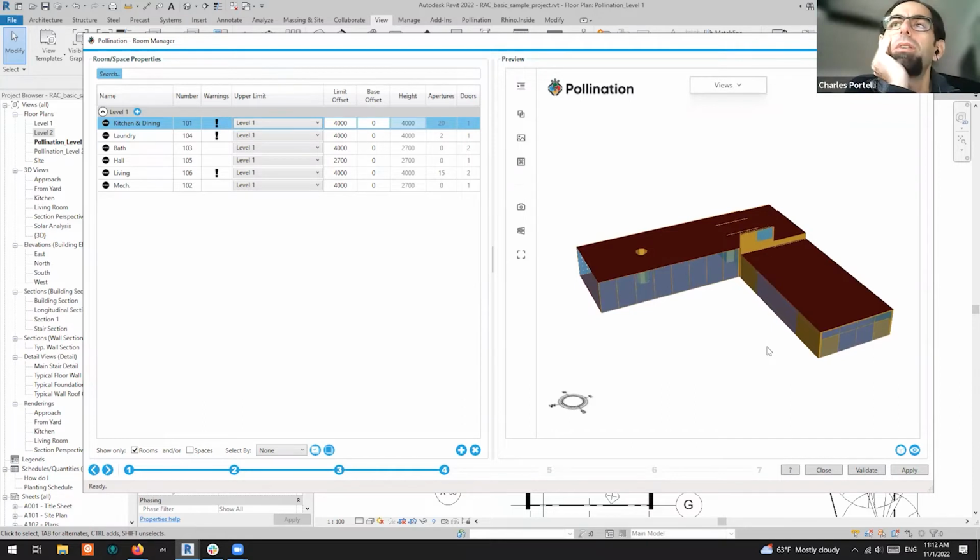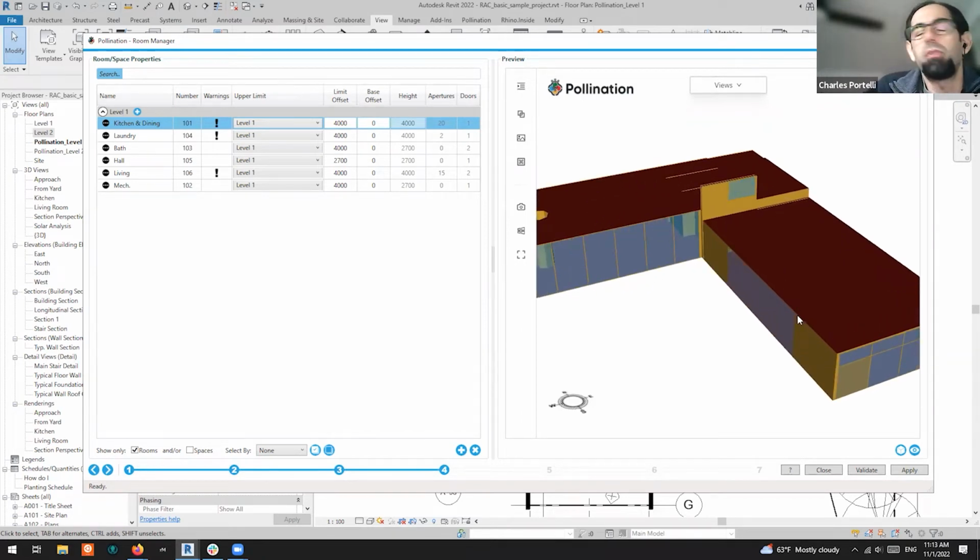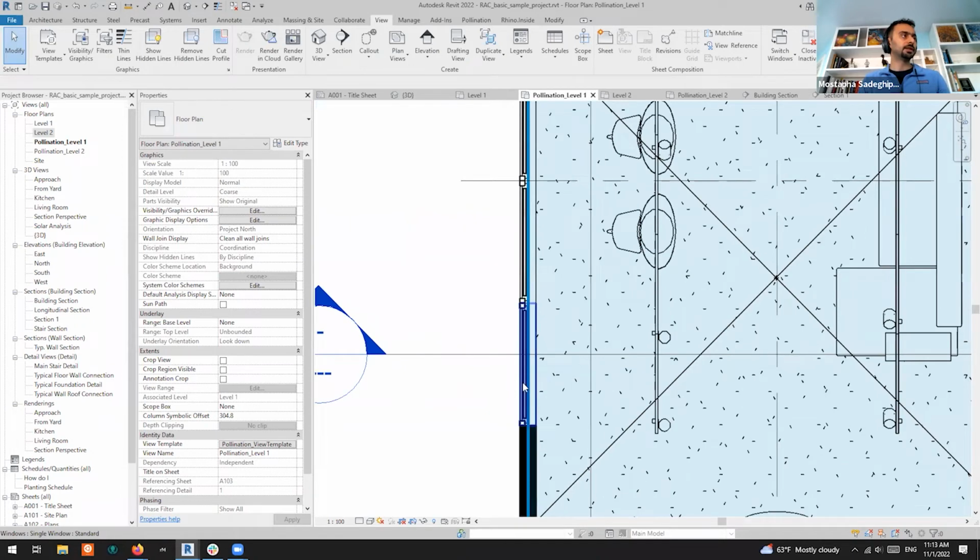Yeah, a quick question. When you edited that floor slab, you edited it in a location where the windows were almost floor to ceiling, right? They're almost full height windows. Would you do the same if the window is just a standard, non-floor-to-ceiling height window? Yes, this doesn't have to do with the aperture. In this case, because they are room banding, the room basically stops here. So it's about the room itself. Whatever your room banding element is, you have to make sure the floor aligns with that. Yes, good question.